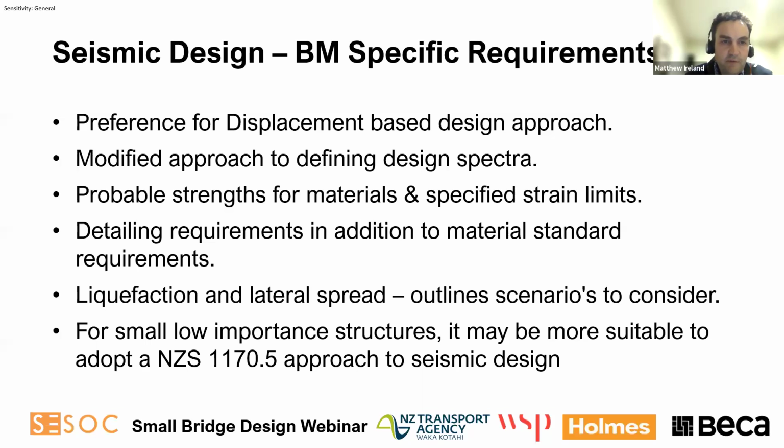So some more things about seismic design in the bridge manual. The bridge manual adopts a preference for a displacement-based design approach, which is a bit different from the normal New Zealand standards. And also, whilst the design spectra for seismic demands is based on 1170, the actual process to determine the design spectra is quite different. There's a number of different factors built into the bridge manual, which you'll need to work through.